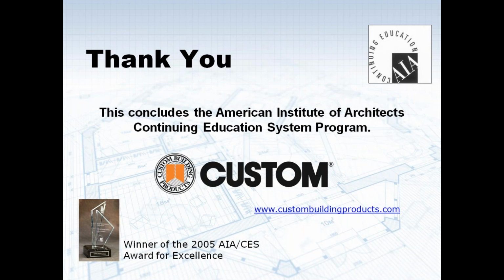In regards to expansion joints over a heated floor assembly, are they the same requirements, 20 to 25 feet interior, 10 feet exterior? Yes, I mean, like I say, you could always use the 8 to 12 interior, which is the safer bet if you're expecting a lot of movement, thermal movement, whether it's from the sun or the heat. But yeah, there's not a change in it. The EJ171 is the same application that applies for the radiant heat, the RH drawings.